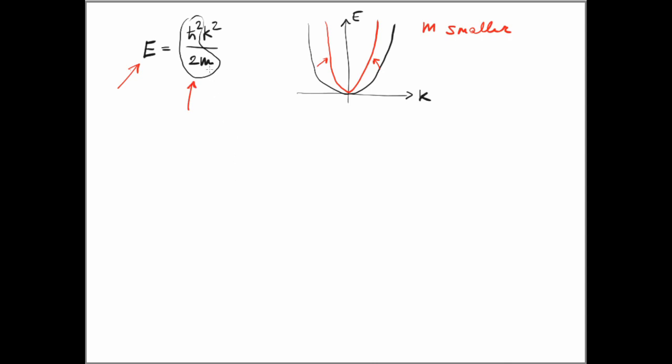So as we can see, if m becomes smaller, the plot of the E-k dispersion relation becomes this one here in red. So a smaller effective mass corresponds to a sharper band diagram. And because we know that the effective mass of the charge carriers in that band is immediately related, if you remember, to the mobility in an inverse relation.